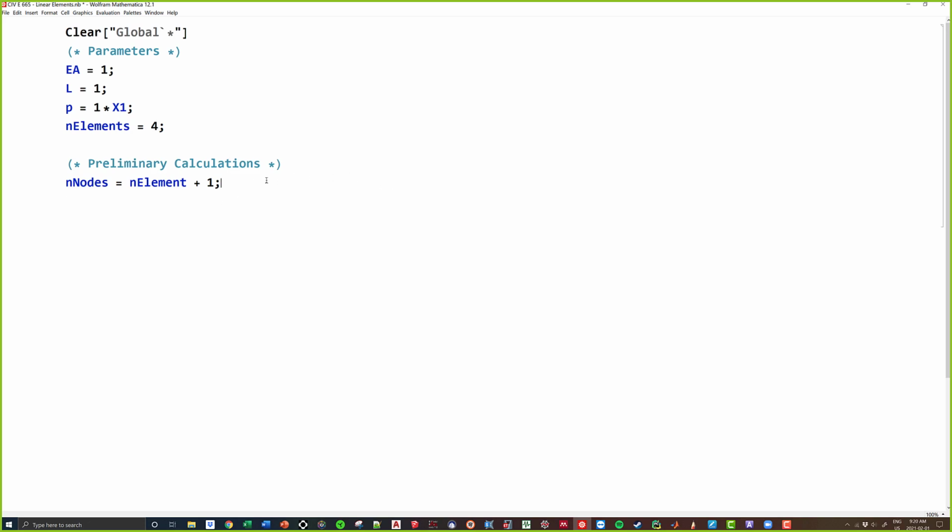So the first thing I'm going to do is define what the element length is. I want the length of one of those elements because, again, that appears a lot. So I'm going to go EL. I'm just going to call this my element length. What will this be equal to? If I know the length of the beam, L, and I know the number of elements, what would be the length of my elements? All right, Sabrina, you're right on. So this is going to be L divided by the number of elements.